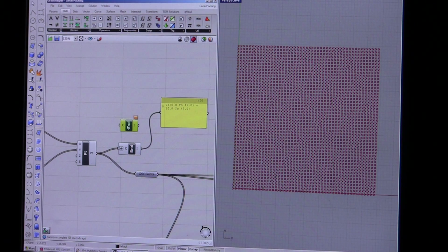So what this is essentially doing is putting a bounding box around the amount of points that we have, and it's giving you the location of the furthest point and the closest point, and then it's telling you how far that step is. So when we grab that, what we want to do is flatten these points. That's what this little down arrow means.